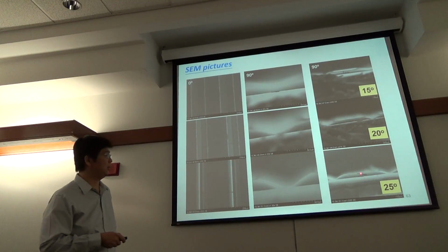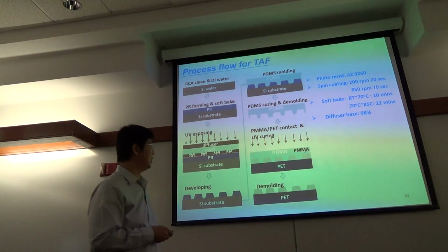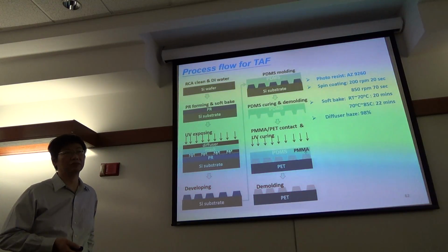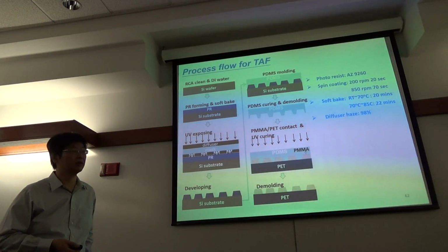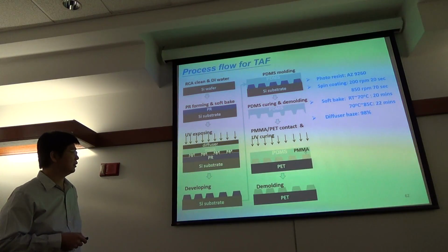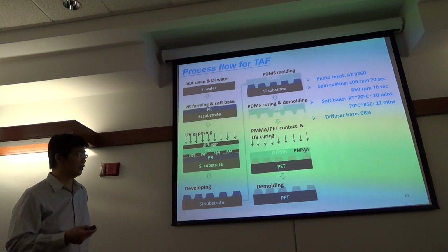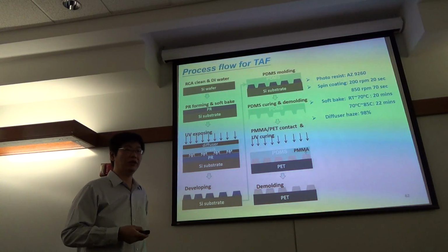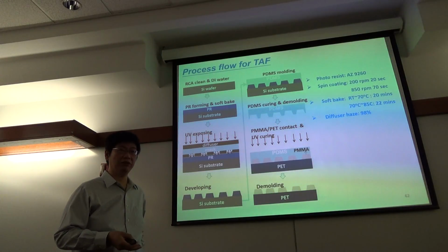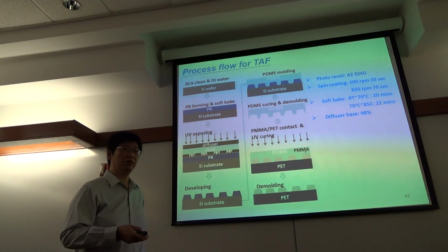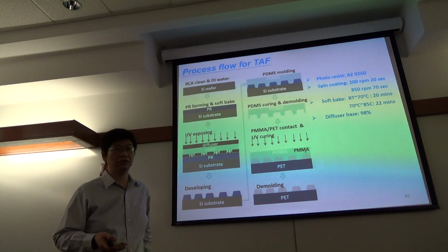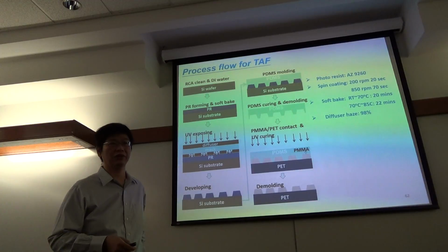For here it's 20 micron, and typically we can have from several micron to around 20 micron, 30 micron. That is okay. And actually, right now we are doing some microstructures. For the typical photoresist, that is one micron to several micron. If you want to go to 10 micron, 20 micron, you need some special photoresist, but still achievable.